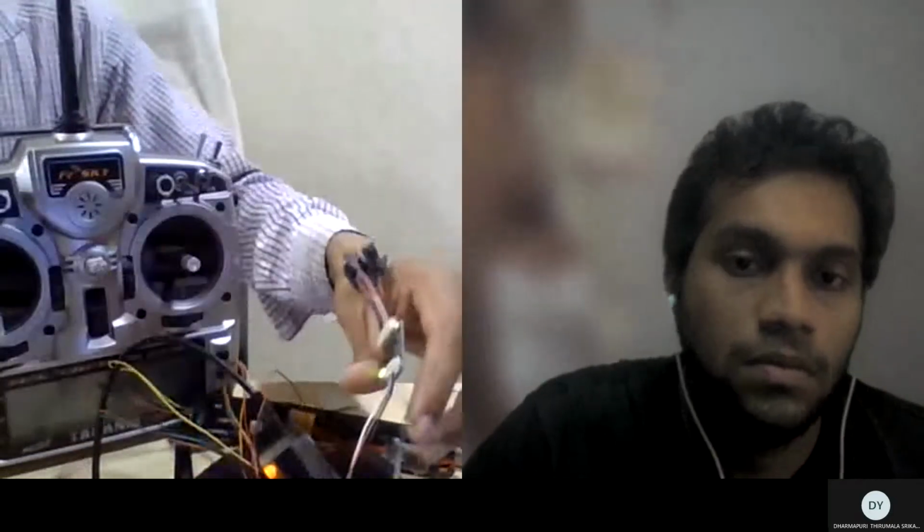All the outputs coming from the receiver side are fed to the flight controller for controlling the aircraft. If you have this type of receiver, then this PPM encoder is not required. You have just a single connection of this type, a USB-style connector, and it will be fitted in the RC in. Only one is needed. That's the one thing.